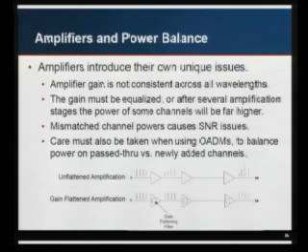So what happens in the amplifiers is after they get done amplifying, they run through a little filter that kind of brings all the signal levels back down to the same level. You need to take care when you're with an OADM system where you have one channel that may have come from 40 kilometers away and you have a new channel that's coming locally. You're going to have very different power levels then. So you need to take care to design your network.